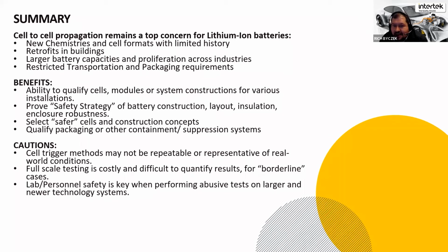Benefits of doing the testing allows us to categorize or qualify or classify individual cells, module constructions, or systems for different types of installations. Again, most stationary systems are somewhat one-off. So if you have a way to qualify a building block, that regardless of how many of those building blocks you put in the same location, you can prevent spread from one to the other, then that's obviously a best case for us. Understand that the different methods we use, although it may be easier to trigger a single cell event, may or may not be easy to implement, or may not be representative of what happens in a unit or module level installation. Full-scale testing is very difficult to do.